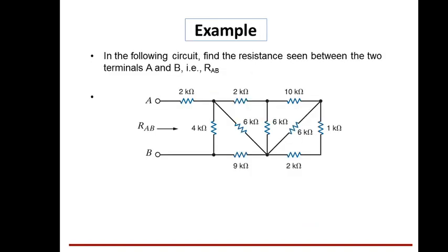Now for this one I will give a hint. Please try. Find the value of resistance. Again it is the equivalent resistance only. Like the first example we did, find it in a similar way. From the right side we start. We see here 1 kilo ohm and 2 kilo ohm, both are in series, so add them to get 3.